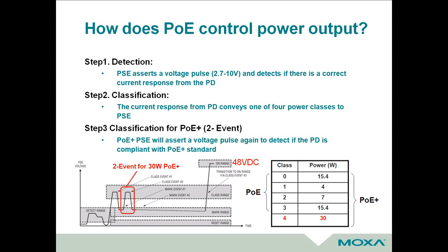Anything outside of that voltage range, from maybe 46 to 51, is considered non-compliant. And there are plenty of proprietary things out there that are non-compliant. We've seen some older Cisco IP phones and stuff like that that work on 24 volt DC. They call it PoE only because there is literally power being put over the Ethernet cable. But that is not standard-based PoE. So it is proprietary. You will need to use their hardware to make it work.